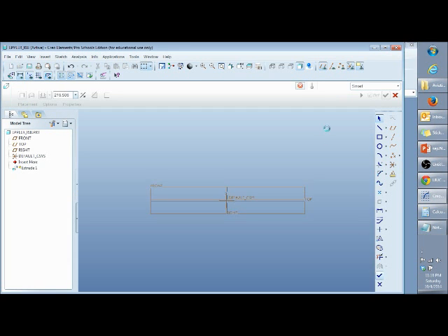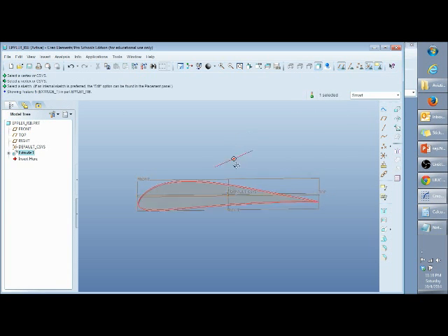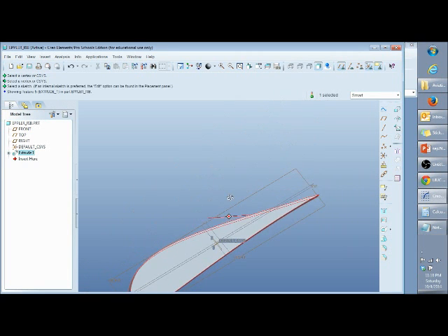So go ahead and click OK. And we'll want to change the length that we have here. I'm just going to make it 1/8, which is a common thickness of a sheet of, say, balsa wood or some such. So go ahead and click OK, hit enter and click OK. So there you go. You have your rib, and that's all.